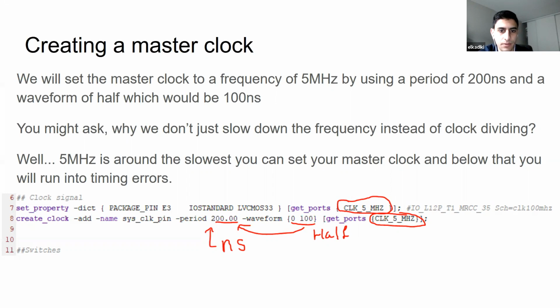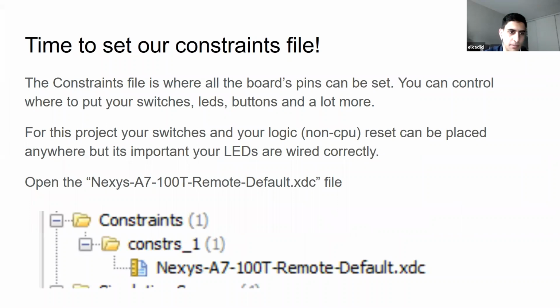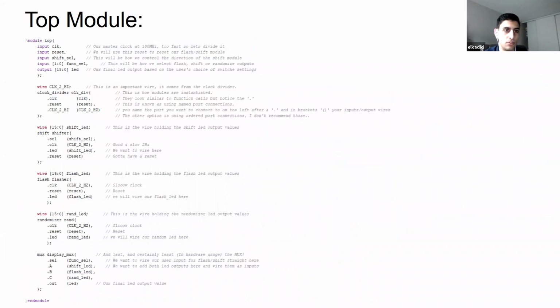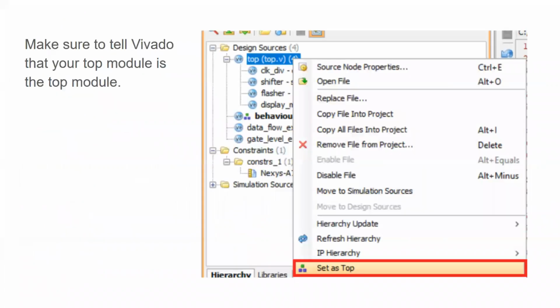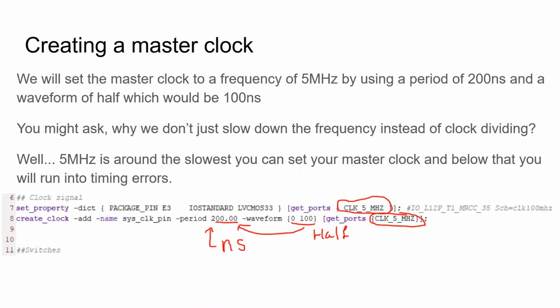I was wondering because CLK is an input for top, so did we get it from here? Okay, that makes sense. It's coming from the constraints file. Imagine it's a switch that's toggling very quickly, but we have to tell that switch how to toggle. And we can't build one in Verilog, so it has to come from the FPGA.